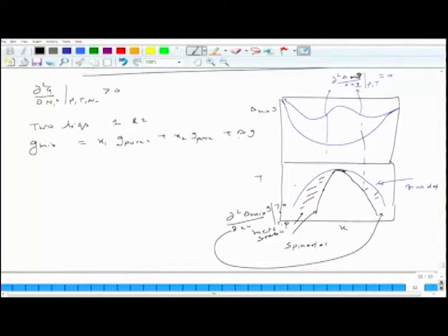Now, looking at this again, this is your point A. So what is happening is, this is concave up, which is stable, and this is concave down. If you have a system that is concave up, it will try to segregate in such a way that it ends up somewhere here. The phase separates such that the composition is closer to this part. So this is your initial composition. It may segregate in such a way that it becomes x1 star and x2 star, and these can of course be connected by a tangent correspondingly. This is something one can also prove.